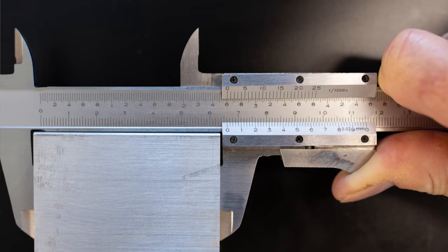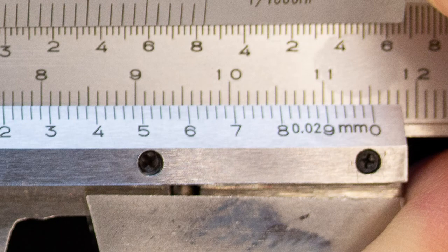It's accurate to, according to the very fine writing on the sliding scale, and again, the index mark is the 0 of the sliding scale, it says 0.02 millimeters. That means it's theoretically accurate to not 1/10 of a millimeter, but 0.02 millimeters, which is 5 times more accurate than even if you could guess, even if you didn't have to guess on a meter stick. So it's like 20 times theoretically more accurate than reading and estimating that last digit on the meter stick.